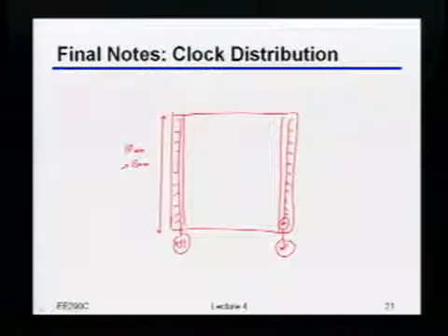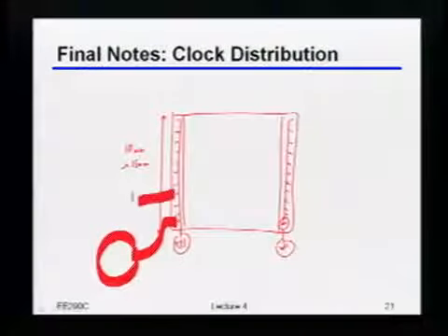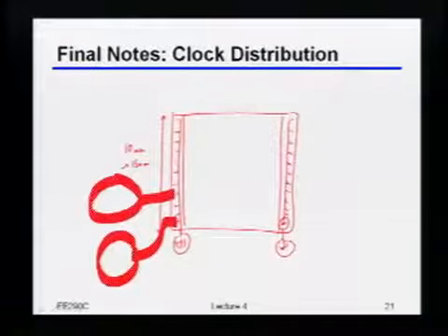But of course that means that locally, each one of those tap points would have to multiply that clock frequency up to get to the very high frequency you need on the actual line rate itself. So you have this trade-off between having just one PLL and amortizing the overhead of that PLL across the entire link, versus distributing the very high frequency clock across that entire distance and paying all of the clock power associated with that.